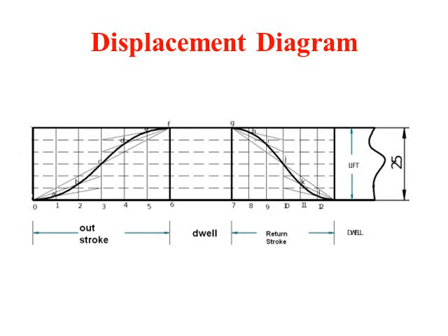Same way has to be done for the return stroke. So these various points A, B, C, D, E, F, G, H, I, J can be next joined by a smooth curve. So that completes the displacement diagram. In this particular figure, they have taken 3 as the center, and the center line is divided into 6 equal parts. They have not named it. We can just name it, give some values, so that it will be easier when joining it.